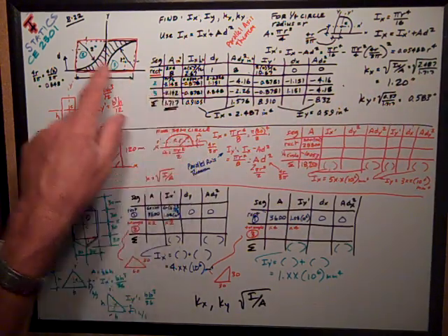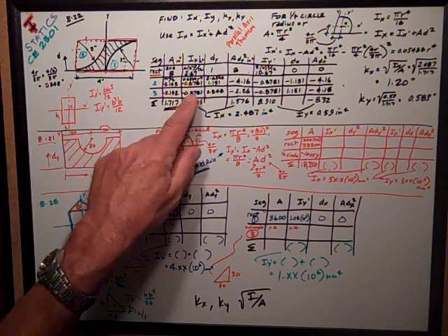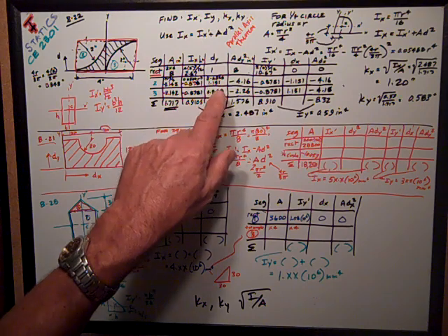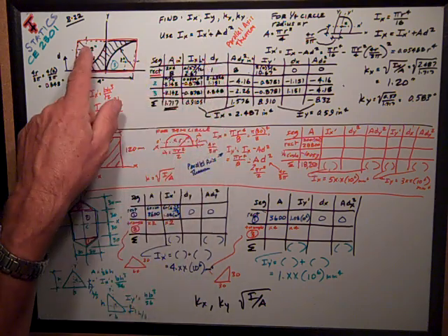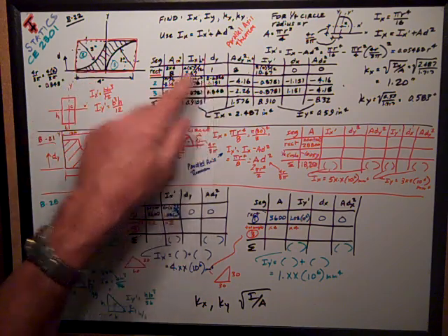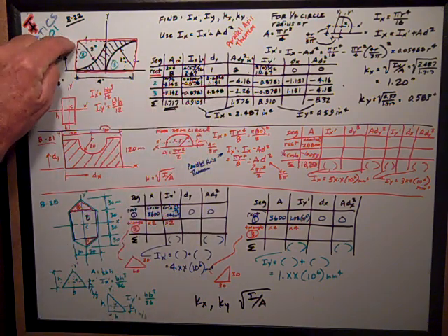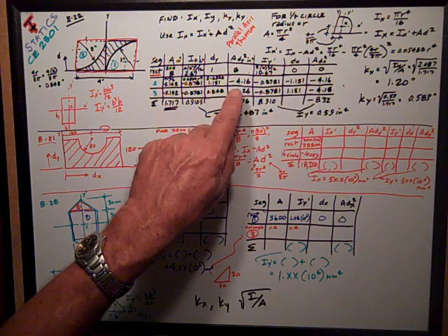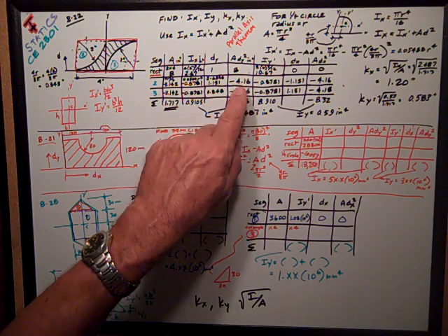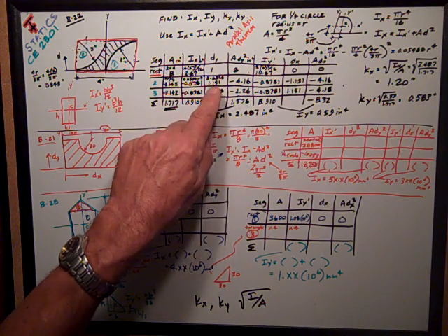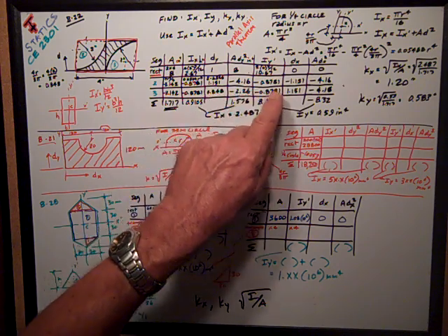And remember, this is a negative area because it's a cutout of that rectangle. Negative 0.078781. The distance from the centroid of the quarter circle to the y-axis is 2, the height, minus that distance, 4r over 3 pi, so that works out to be 1.151. Do the AD squared term for it. The area is negative times this number squared, negative 4.16.